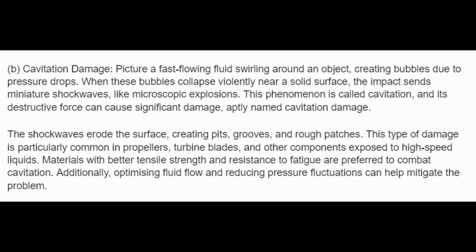The shock waves erode the surface, creating pits, grooves, and rough patches. This type of damage is particularly common in propellers, turbine blades, and other components exposed to high-speed liquids. Materials with better tensile strength and resistance to fatigue are preferred to combat cavitation. Additionally, optimizing fluid flow and reducing pressure fluctuations can help mitigate the problem.